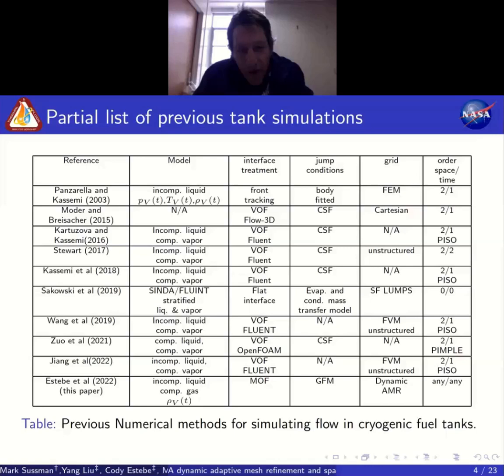Our question is, if one is taking large time steps in the gas, then perhaps the resolution of the acoustic waves is not going to be accurate if the time steps are larger than the CFL condition needed to meet the stability condition for the acoustic time step.